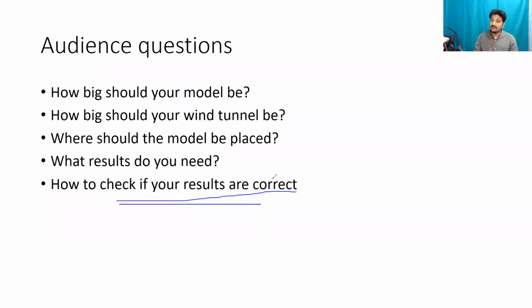That's not that easy. Your experiment should be extremely controlled, right? You need to travel exactly at the same speed. The wind speed should not affect. You will have uncertainty. Your pressure sensor data needs to be calibrated. All those things need to be done, which is why people use a wind tunnel where everything can be controlled. Because all these sensors are also sensitive to temperature variation.